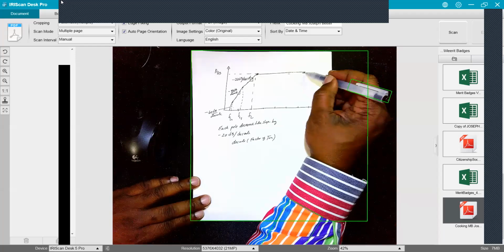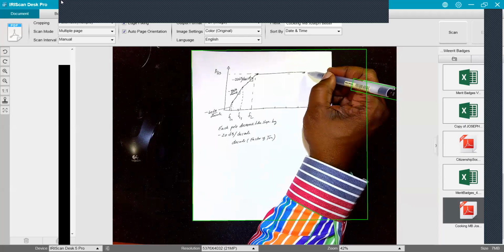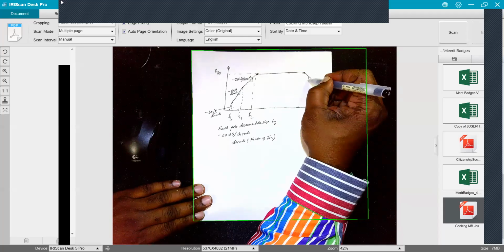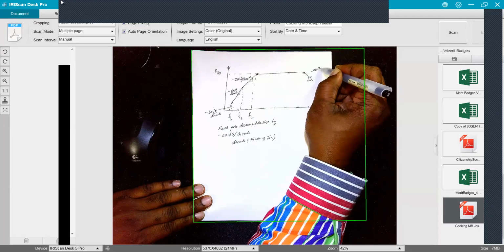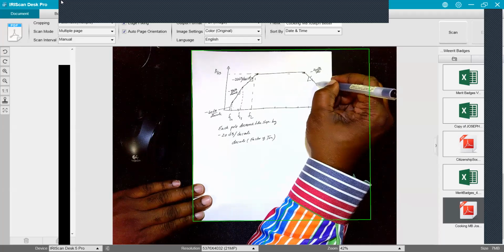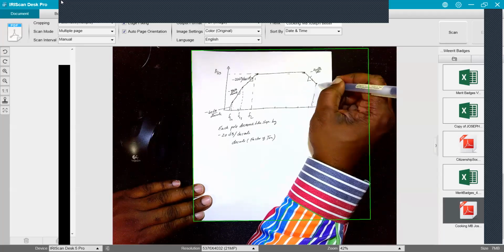So we have the same thing here at high frequency. Our first pole that kicked in here rolls off at minus 20 dB per decade. And then at some point we get a second pole that's located at this point frequency.